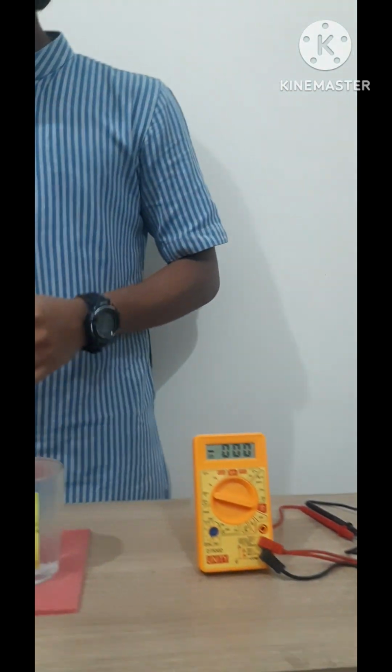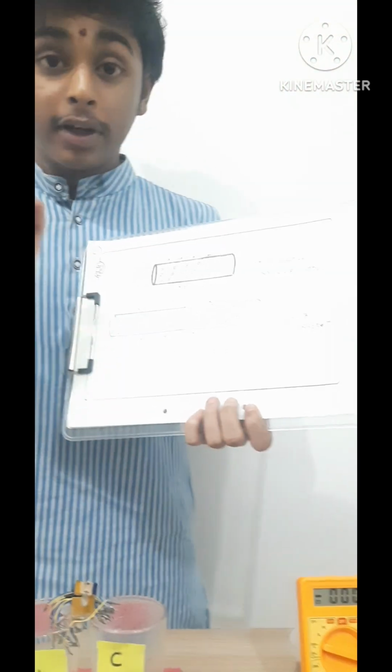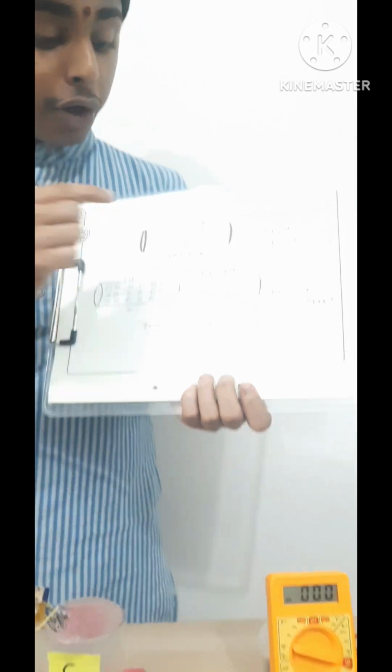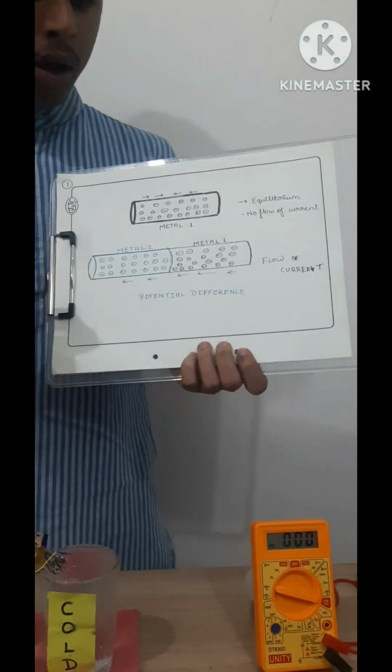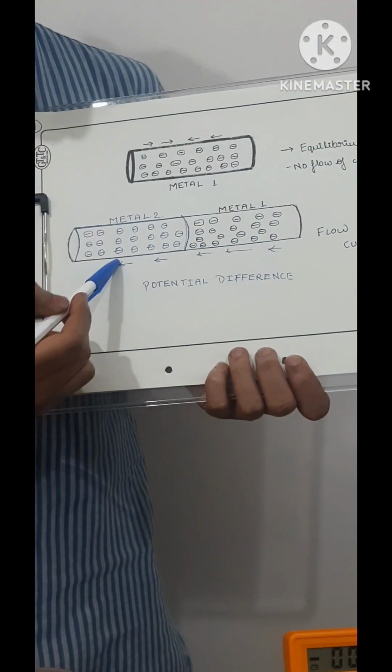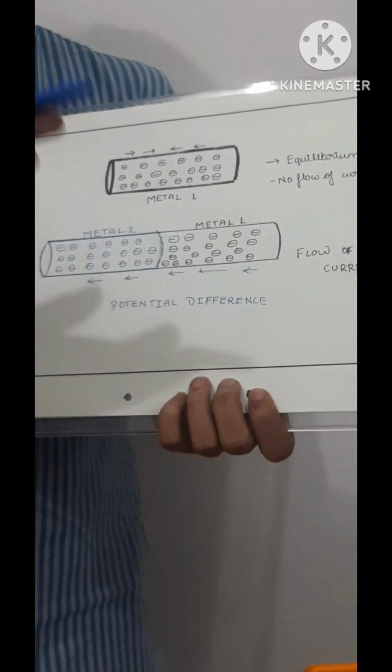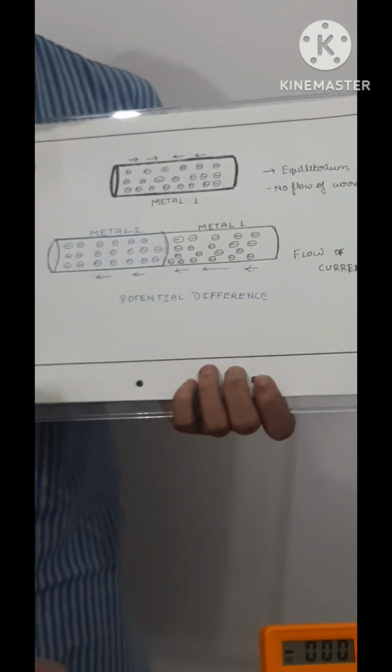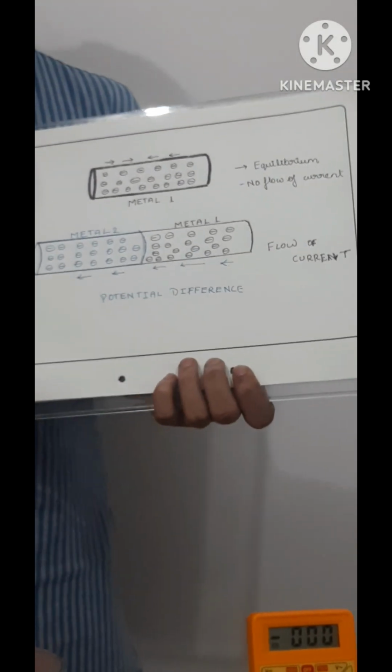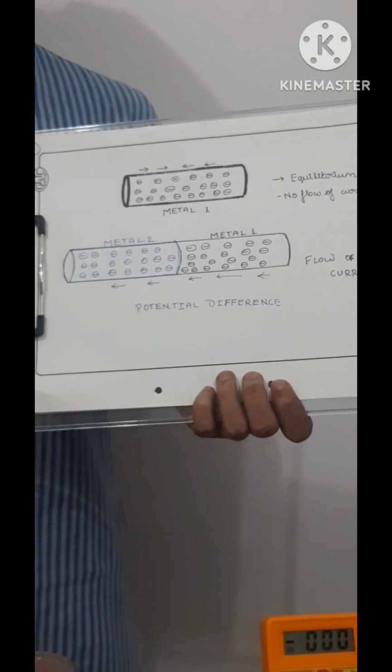Creating a temperature difference across a similar type of metal will not produce voltage because the electrons equilibrate due to the homogeneity of the medium. When we connect two different metals together, the electrons tend to move towards one of them because of the difference in the chemical composition of the two, thus producing voltage.